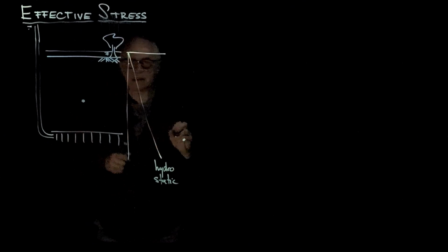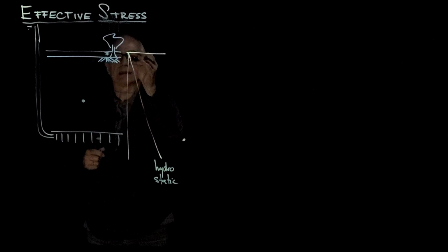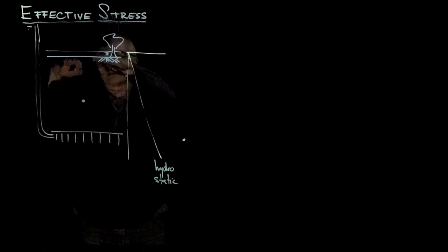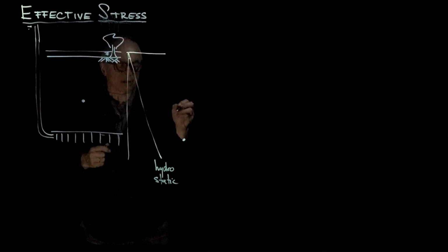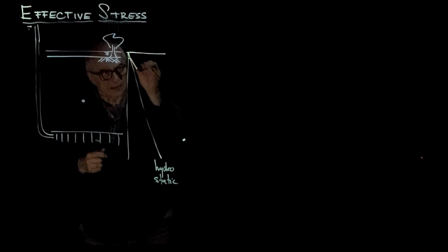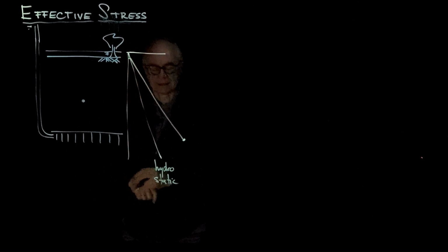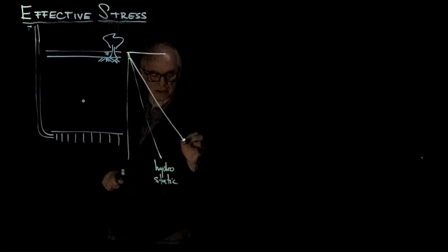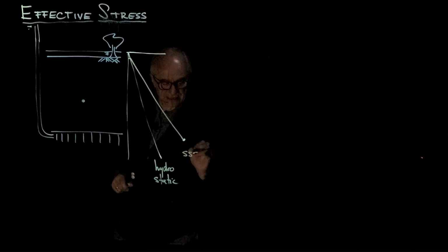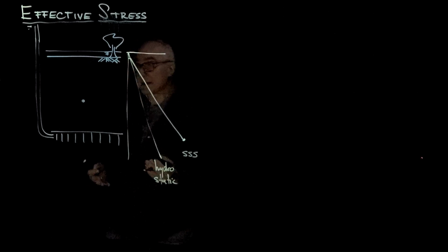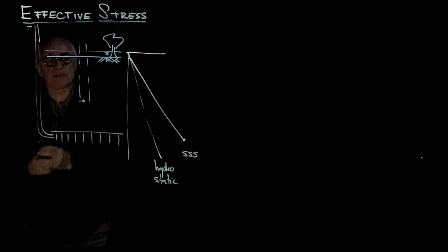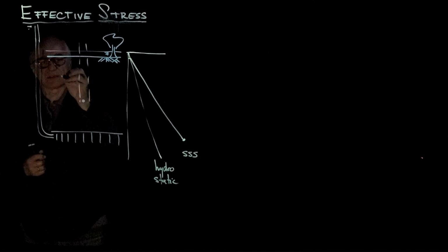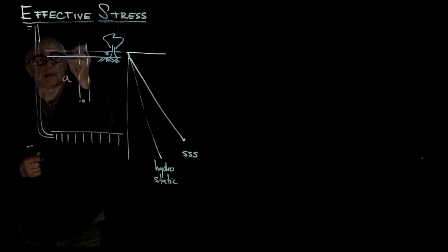But just for the sake of putting the pressure only, the pressure at the top will increase according to hydrostatic conditions, given the fact that it's a slow flow and that the lake is holding that pressure at the top. But if you look internally, the pressure is going like that. And so this is when there is an Artesian and there is a steady state seepage. If you want to analyze this case, once again, the total stress at the point is the weight of everything above the point, which is due to, let's say, A and B heights.